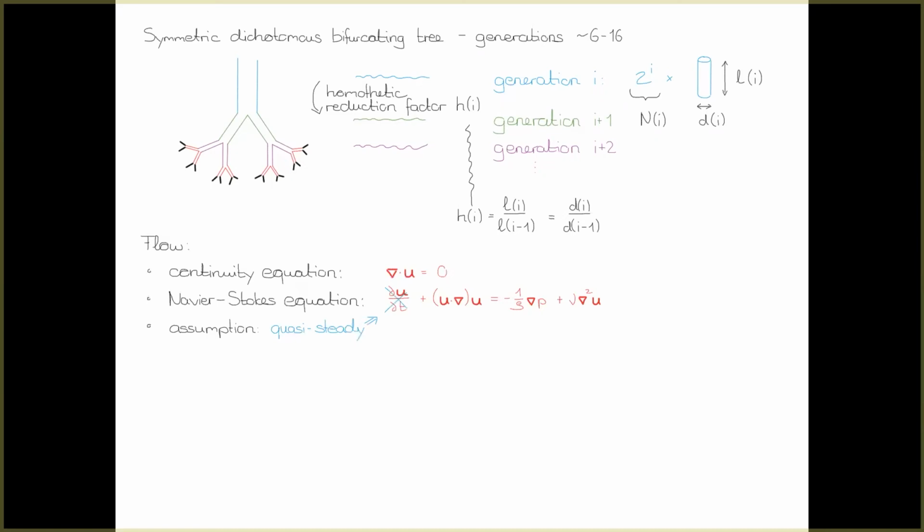This comes from our analysis where we looked at the Womersley number, which is small enough that we can justify this simplification. And then we are basically left with a steady state Navier-Stokes flow. And because the Reynolds number is small enough, we have a laminar flow. We assume that we have this Poiseuille law, which we can use. And that simplifies the fluid dynamics tremendously.